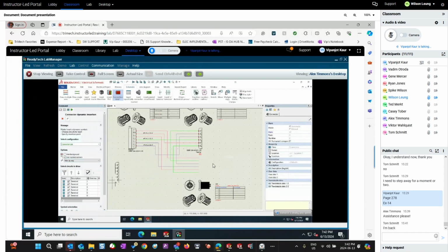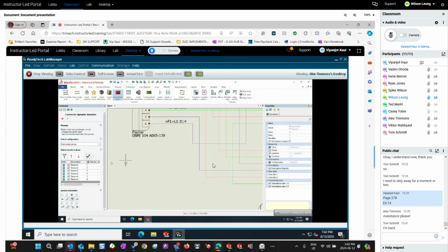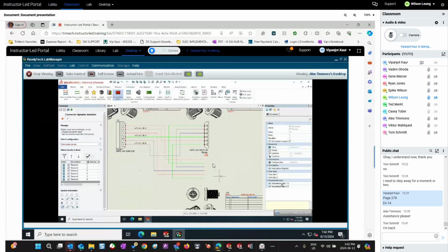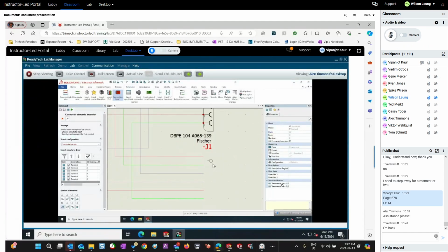They're saying insert 1 pin at a time. Change your configuration. We don't need a D-shaped symbol, and change it to 1 symbol per pin, the second last one. Good. So you've got 6 pins selected. Flip your book onto the last page of the exercise. Your pins should be in that orientation. So right click, flip couple times. Good. One more. This looks better. On the very right of this sheet, you should see the wires that are not connected. I want you to drop it there, zoom on it. So click on the first one on the top.